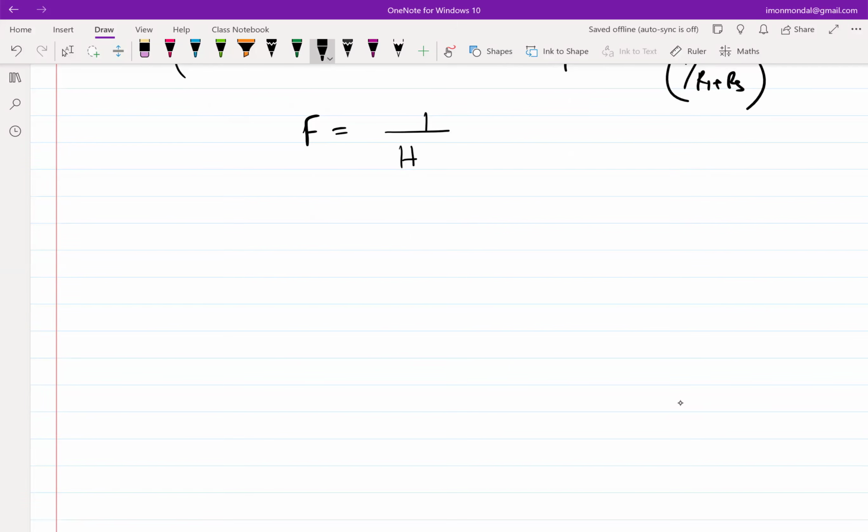So I will just show a mixer. Let's assume it's an ideal sinusoidal mixer. When I say sinusoidal, I mean it's not a square wave. The fundamental thing that you are multiplying with is a sine omega LOt or a cosine omega LOt.